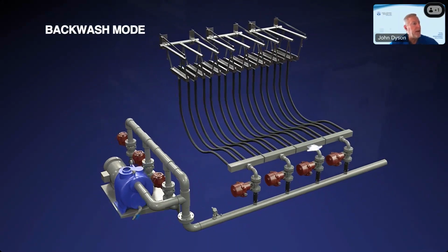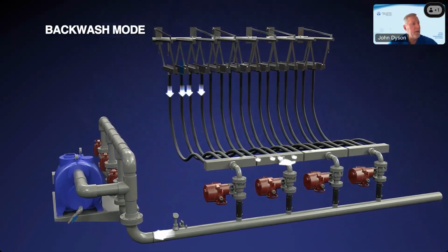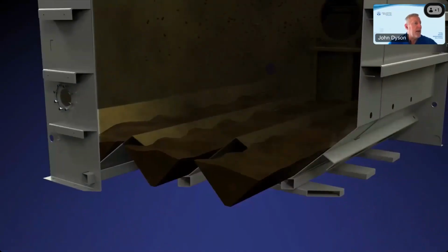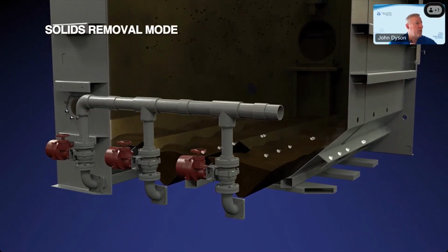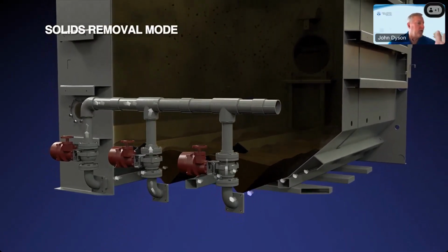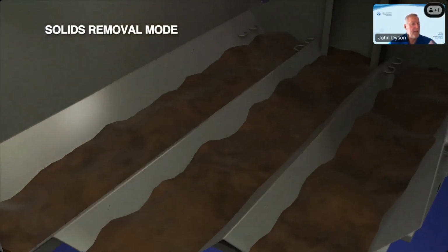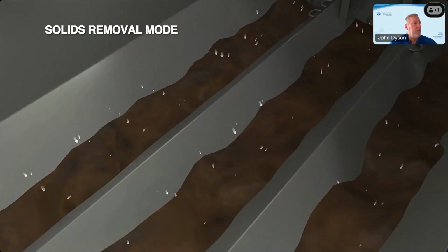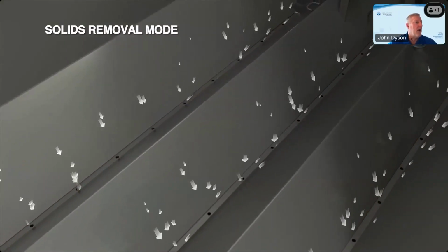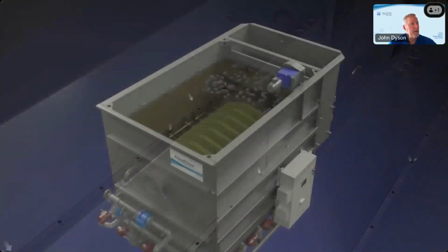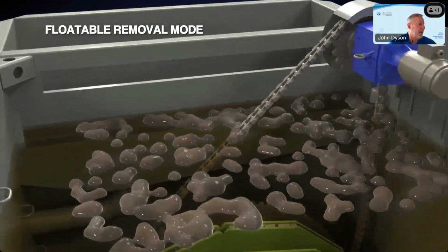This is just showing an 8-disc system where we wash 2 discs at a time, one after the other. If we had a 24-disc system, we wash 8, 8, and 8. As I mentioned earlier, those settleable solids that have settled down between the segments and the walls settle into hoppers that have a steep slope on them. That steep slope allows some concentrating to occur and gives room for storage for periodic extraction. Generally, that's every 8 to 10 backwashes, and you suck those solids out. You basically just want to prevent a blanket of sludge from forming in the system.